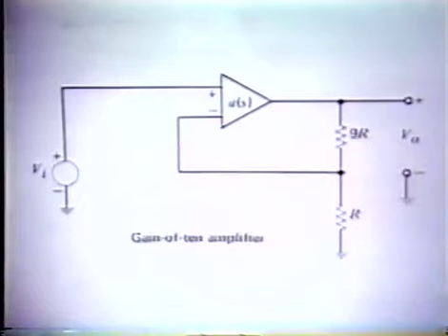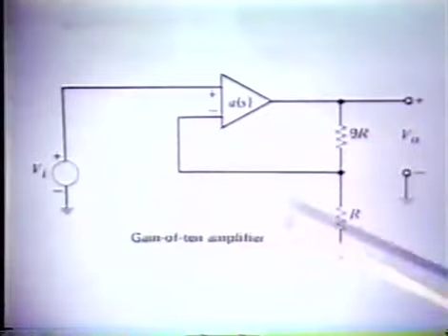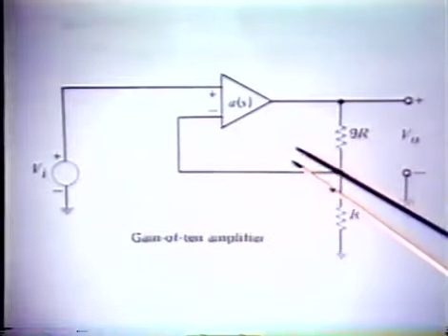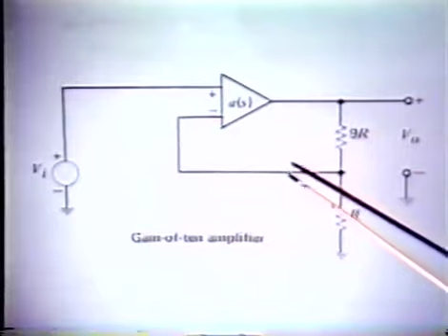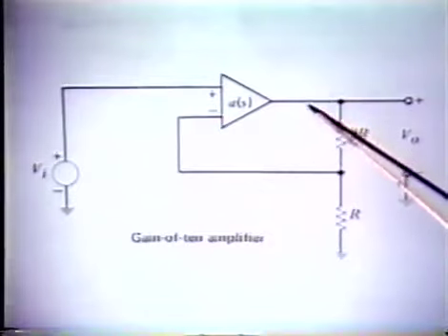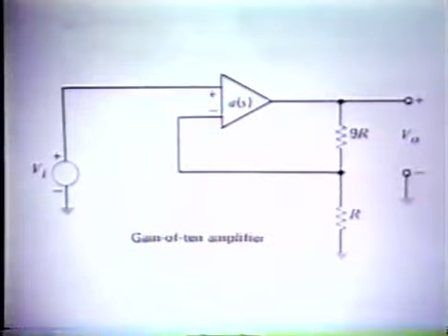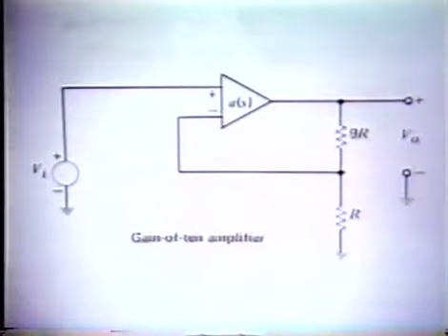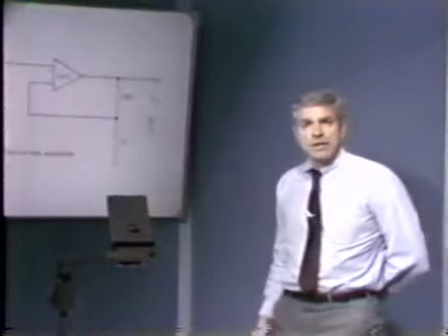Here we see a resistive attenuator, and we recall that the topology of a lead type network was in fact a resistive attenuator that had a capacitor included. So we can get a lead type transfer function associated with the feedback path with F by connecting a capacitor across the 9R valued resistor. So that's not quite the same in terms of closed loop response. There's a little bit of change in zero location as if we were able to get the lead type transfer function in a forward path. But certainly in terms of improving the stability of the system, we'd be able to do it via this method.